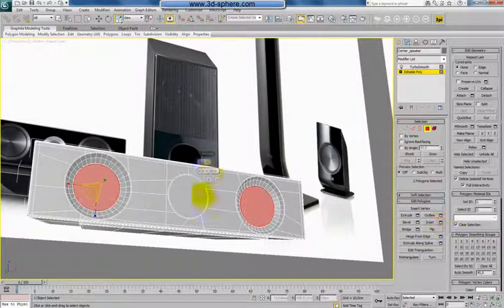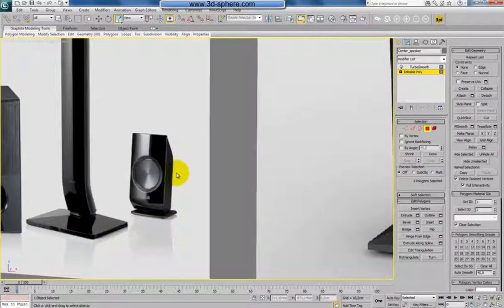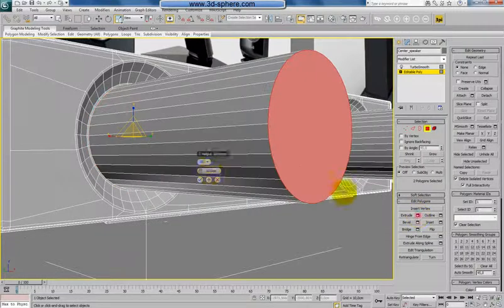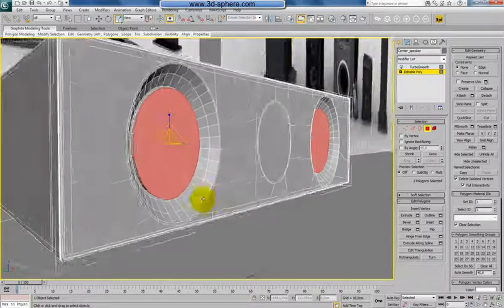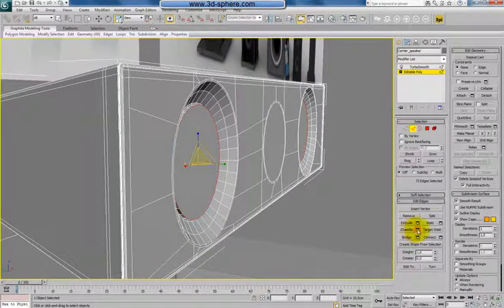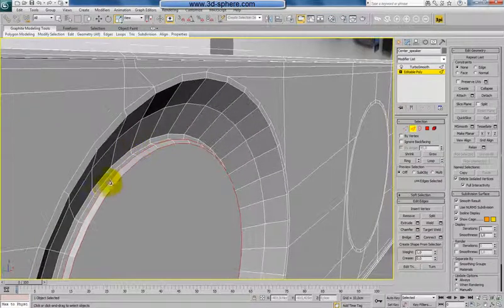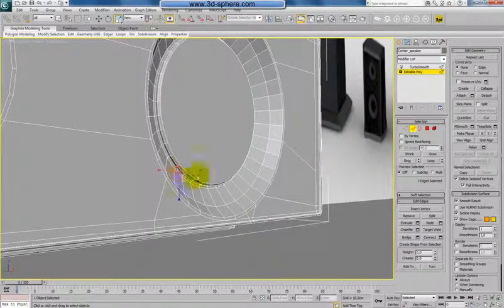Now, again, I will select both, apply a small chamfer, and according to this, there is actually just a circle, a bit conical. So I will extrude it. I don't know, like this. Should be fine. Control H, chamfer, and now I will chamfer also the rest. That means that I will select this here and also this here, loop that, chamfer with the smallest value.